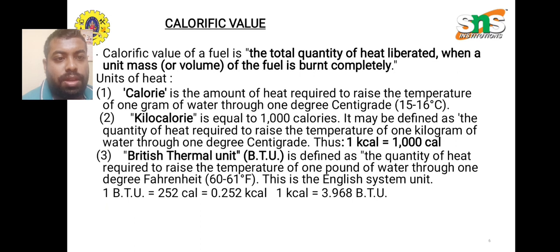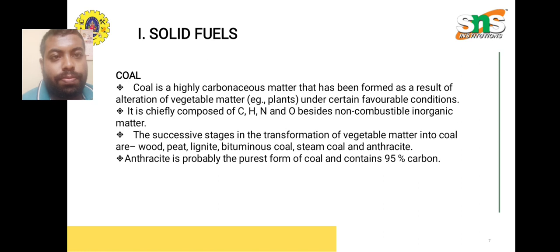1 degree centigrade. 1 kilocalorie is equal to 1000 calories. BTU, or British thermal unit, is defined as the quantity of heat required to raise the temperature of 1 pound of water through 1 degree Fahrenheit, that is from 60 to 61 degrees Fahrenheit. This is an English system unit. 1 BTU is equal to 252 calories, which is 0.252 kilocalories. 1 kilocalorie is 3.968 BTU, which is British thermal unit.